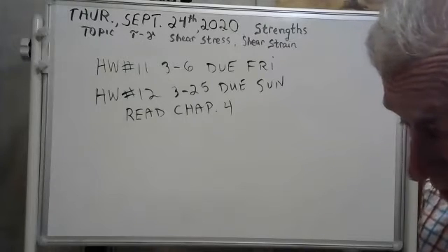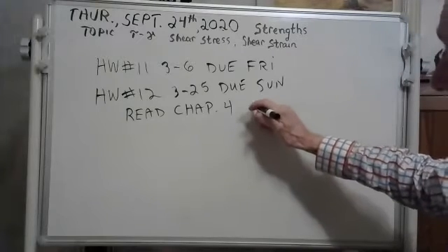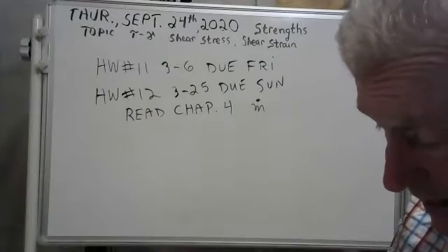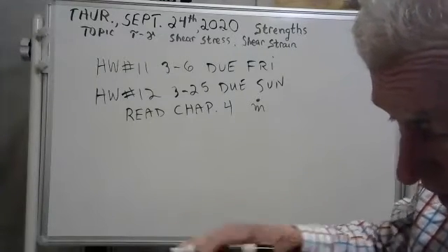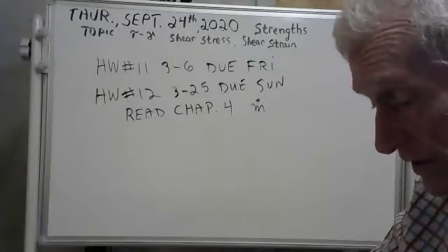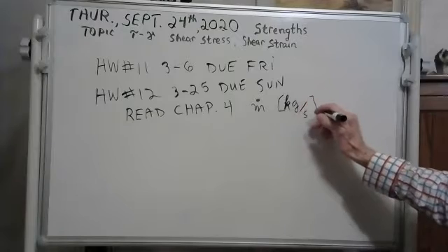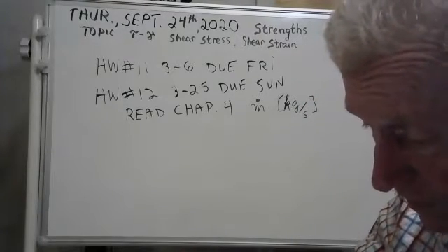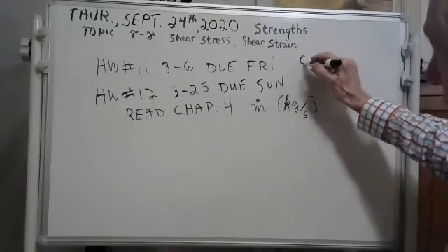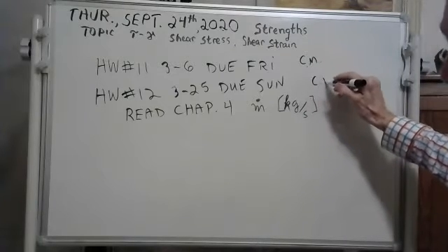It's all about control volumes, mass flow rate, m dot. What that means is mass flowing into or out of a system per time. It's kilograms per second. And we're going to be studying that. We're going to enter the exciting world of control volumes. Up till now, everything we've done has been control masses. But we're going to enter the world of control volume.